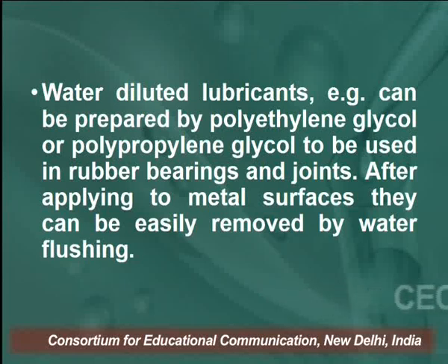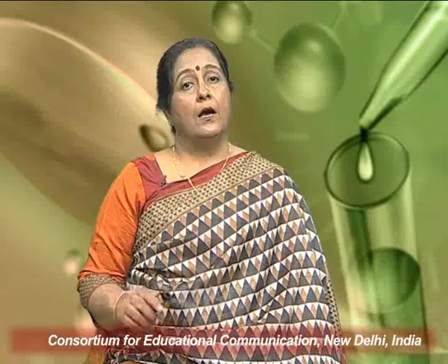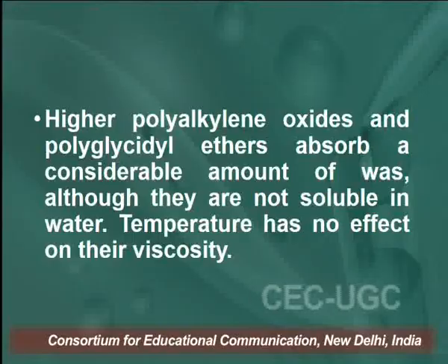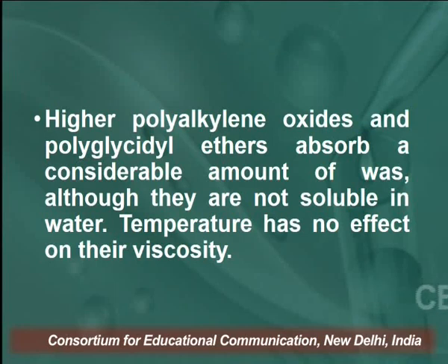Water-diluted lubricants, for example, can be prepared from polyethylene glycol or polypropylene glycol to be used in rubber bearings and joints. After applying to metal surfaces, they can be easily removed by water flushing. Higher polyalkylene oxides and polyglycerol ethers absorb a considerable amount of water, although they are not soluble in water, and temperature has no effect on their viscosity.